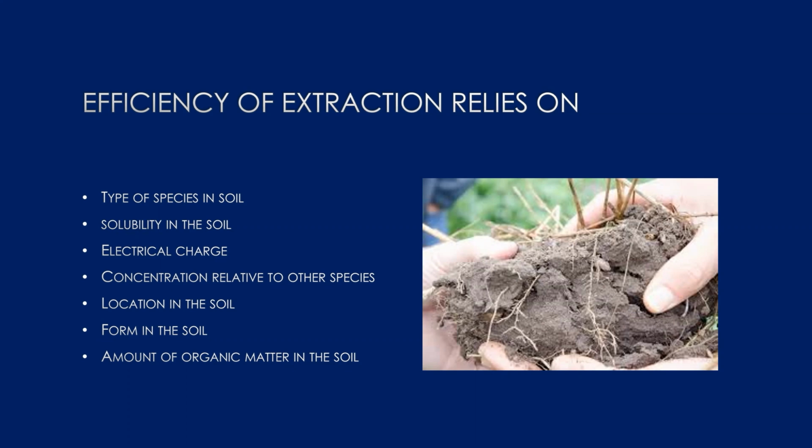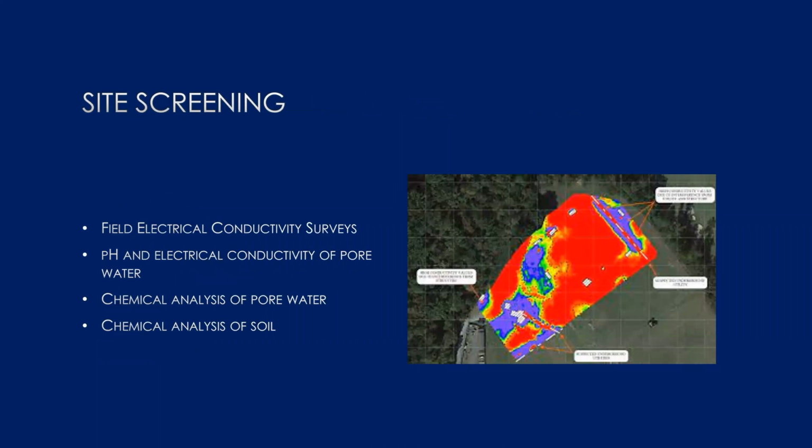Aquifers with zones of low hydraulic conductivity and high clay content are where electrolytic processes are most applicable. A low cation exchange capacity and low salinity also increase the efficiency of the technology. Various field and laboratory screening tests are conducted to determine the physical characteristics of the aquifer that either limit the applicability of the method or which make the method particularly useful.